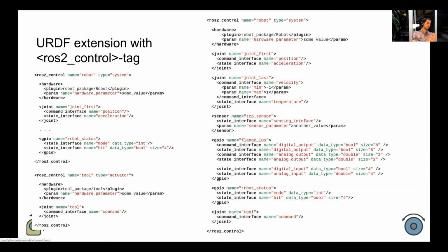If you have some tool on the robot which you can control through micro-ROS, and you want to synchronize this with robot movement and do this in a unified fashion, then I would go for ROS2 control, basically. Maybe at some point we set up ROS2 control on a microcontroller also, but this is probably hard to do currently.